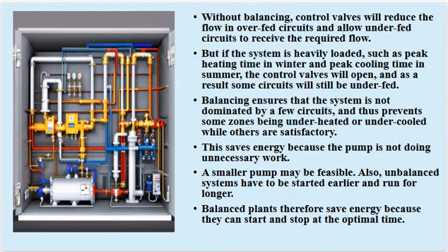Let's continue hydronic balancing, emphasizing that without proper balancing, control valves may reduce flow in overfed circuits while underfed circuits struggle to receive adequate flow. However, during peak demand periods, such as winter heating or summer cooling, the control valves may open fully, leading to some circuits still being underfed.